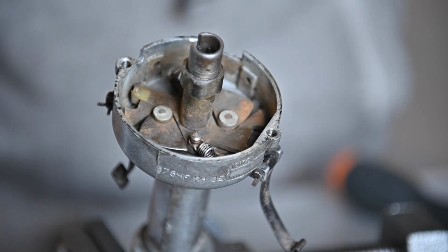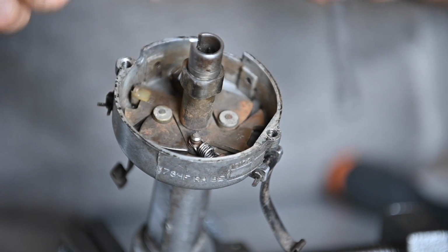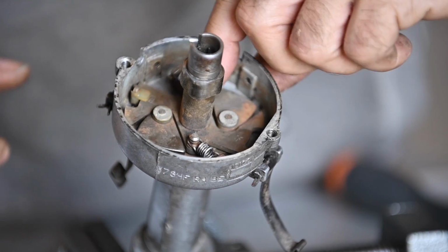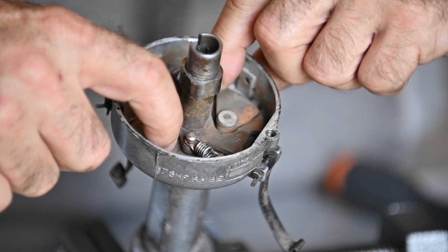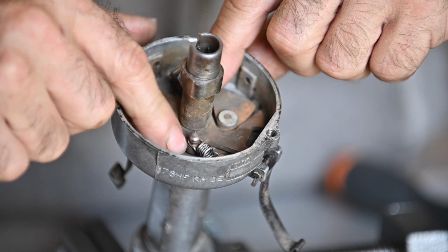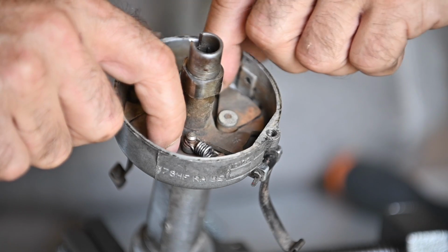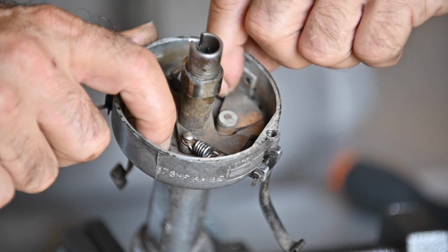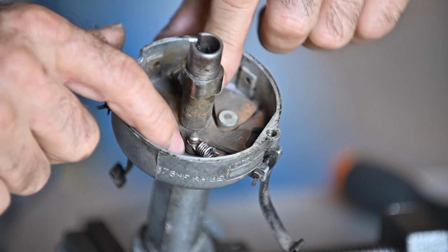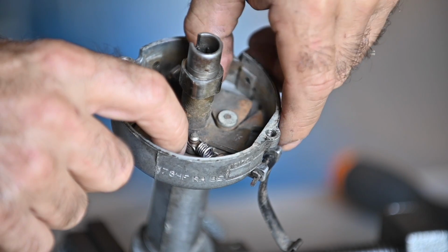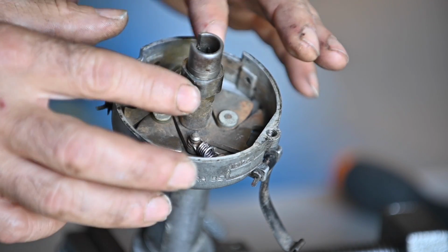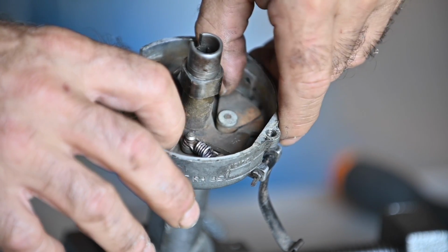Oops, I dropped my screwdriver. That's all right. Inside, here it is. You see these moving parts here? These are the bob weights. And look, when they fly open because of the centrifugal force, look what the notch is doing. If they fly open because of the RPMs, the notch is advancing. That's exactly what bob weights do. The faster the engine runs, the more effect you get from the bob weights. The more centrifugal force you get, the more advance you get on the notch.